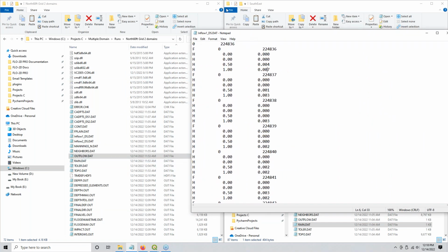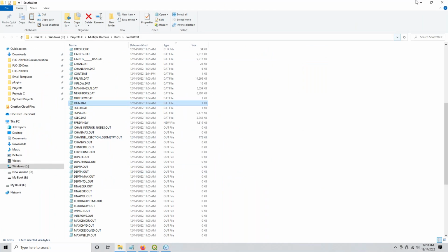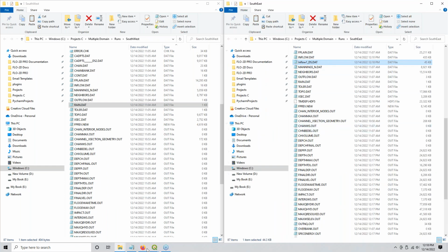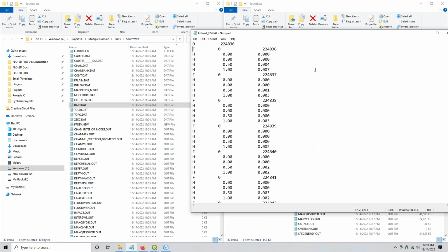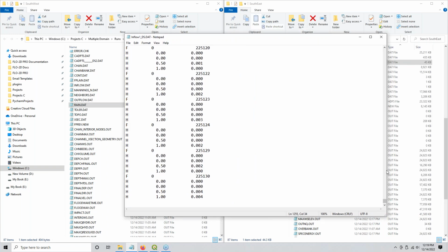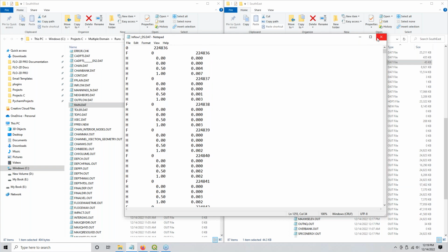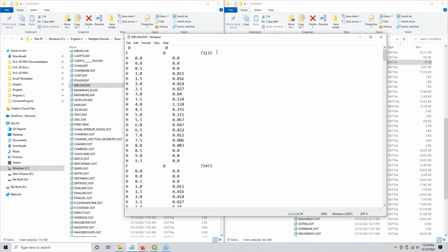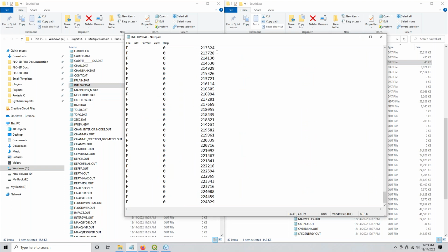So let's go to the downstream model for a sec. This is our Southwest downstream model. And this is our Southeast upstream model. Here is the inflow.dat from that. I just want to take these lines, so I'll copy these lines, Control Shift End, and copy. I don't want that first control line, because it's already in the other one. So I copy that and take it into the Southwest model and go Control End.